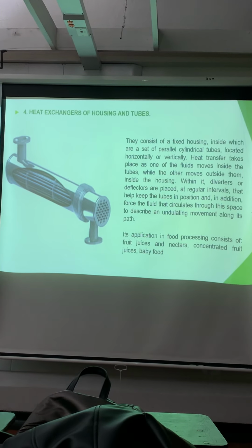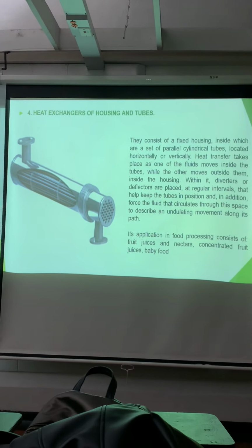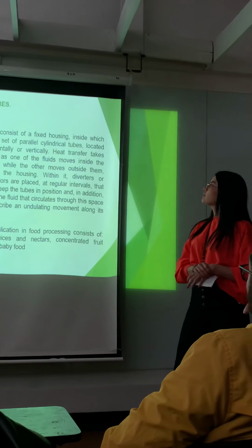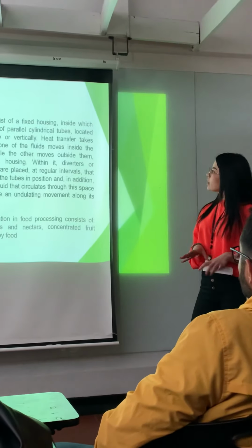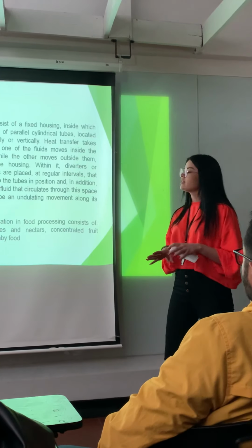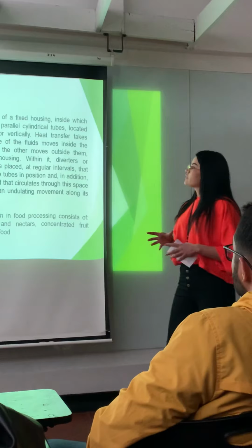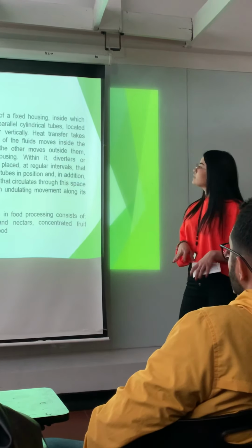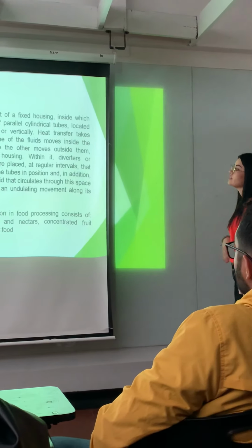And four, shell and tube heat exchangers. They consist of a fixed housing inside which are a set of parallel cylindrical tubes located horizontally or vertically. Heat transfer takes place as one of the fluids moves inside the tubes while the other moves outside, inside the housing.